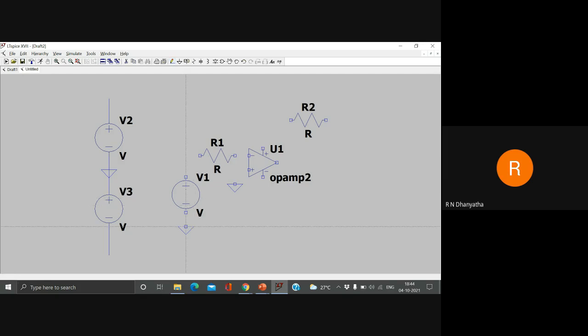So connect the ground voltage source, connect this with the resistors, connect this to the inverting terminal, and then the non-inverting side of the op-amp is grounded now. Connect the feedback resistor to the inverting terminal. Perfect. So everything seems fine. The only thing that is left is plus and minus VCC. So let's see how we could connect that.